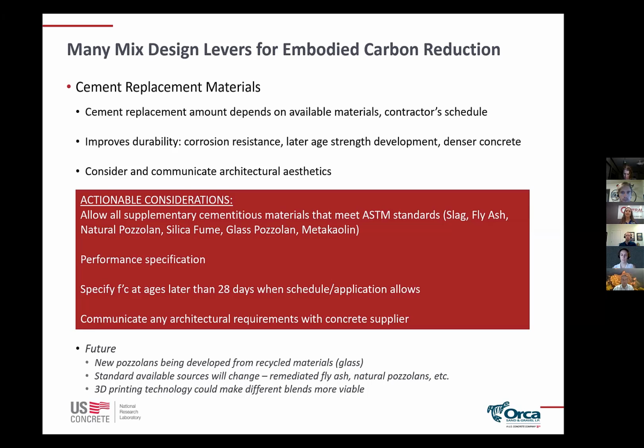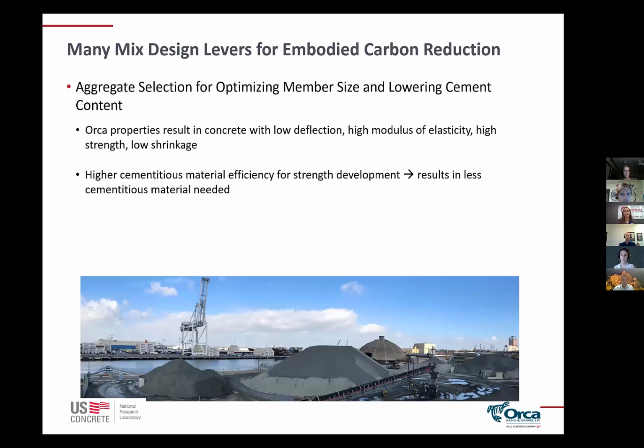And then something that I think is interesting is that I see a lot in terms of 3D printing technology, kind of still at the university and research level. But if that type of technology starts to get utilized, it could actually make different blends more viable, or different blends are going to be better applicable for that sort of placement application. Then, as we've mentioned, aggregate selection for optimizing the member size and lowering the cement content is another lever that a mix designer can utilize.